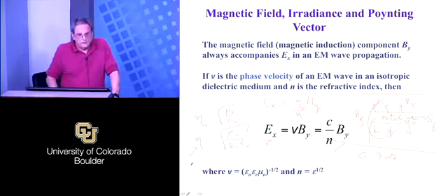As soon as you get to the point, though, where the wavelength starts being comparable to the circuit dimensions, unless the line that you're on has an impedance that's lower than 377 ohms, you're going to be in trouble, because the wave always sees an impedance of 377 ohms at infinity. And hence why we have 50 ohm lines and 75 ohm lines.